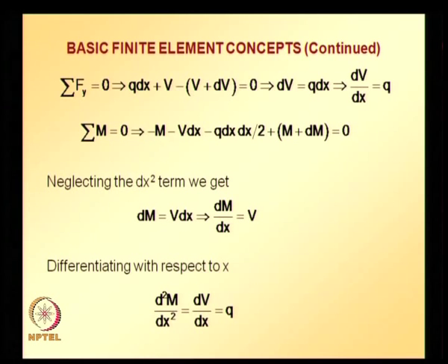This equation gives us a relation between moment, shear force and the distributed load applied, but we want to solve for displacements because of the transverse load. So, we need a relation between moments and transverse displacements, and moments can be related to transverse displacements by considering the beam deformation shown here.